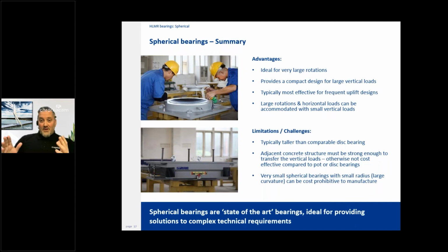And yep, just a summary of the spherical bearings. They're ideal for very large rotations. There would be instances where a given rotation would be hard to do without a spherical design, so this is a particular application that's good for that. They do provide quite a compact format, but it's important to understand that you still have to distribute this into concrete.